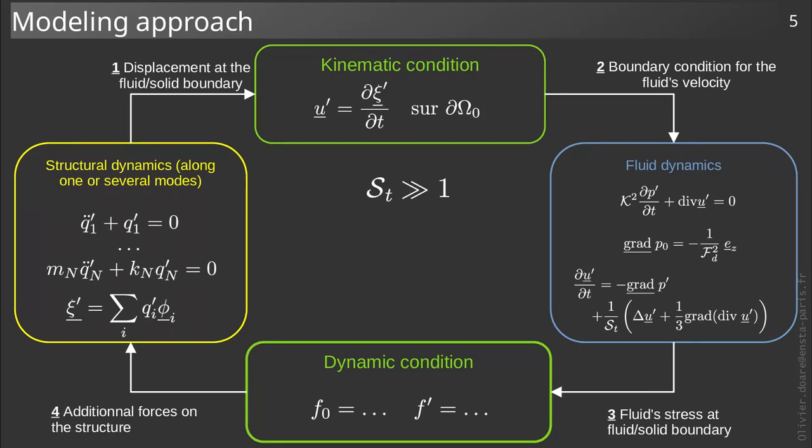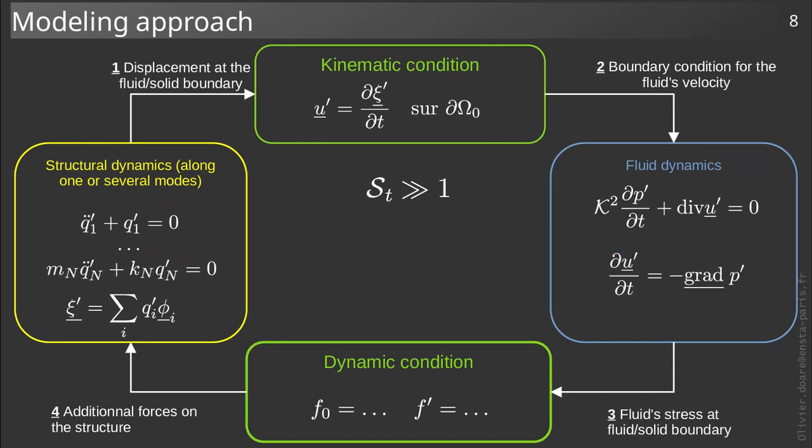We then simplify the momentum equation by neglecting the viscous terms once again, and we notice that the equation describing the stationary state is independent. We can therefore set it aside for this study. Since we are dealing with an inviscid fluid, it is again possible to transform the kinematic condition by being interested only in the normal velocity, since sliding is allowed.